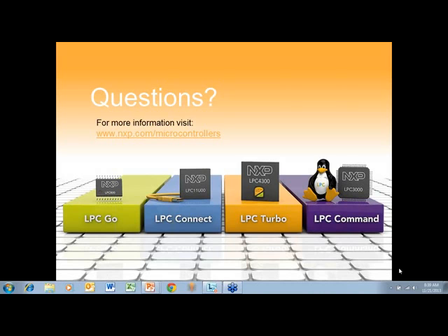Yeah, Gordon, there are a few questions that I'm still working to answer in the list. One is concerning random access through the SPIFI interface and using at the same time the quad SPI externally, for example, in a graphics application. This is a good question. A lot of times in a graphics application where you have images stored externally, those are typically accessed in a linear address mode or contiguous addresses where you have one file, for example, that contains an image. So you'll get best performance by accessing the quad SPI flash in a linear fashion like this.